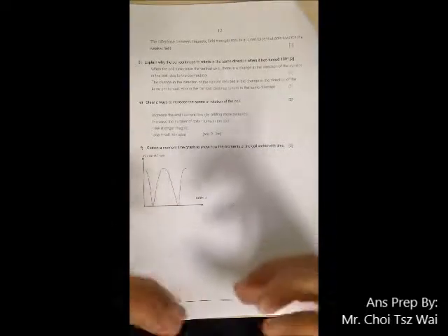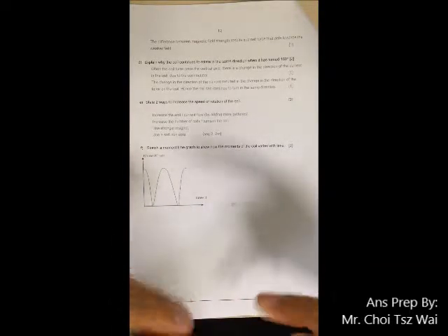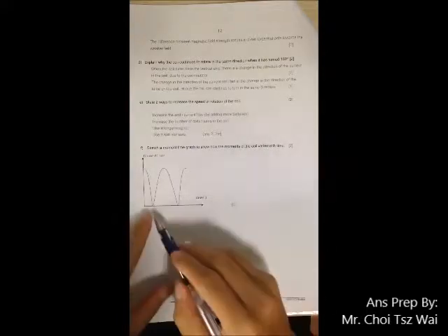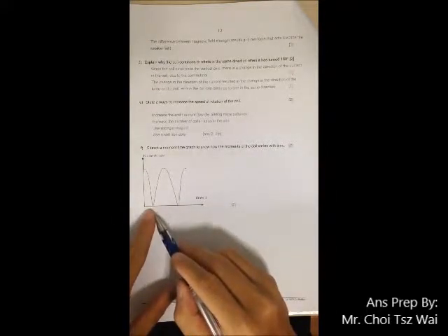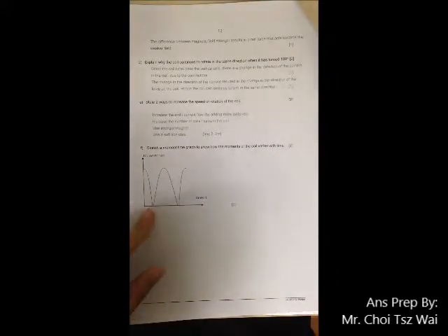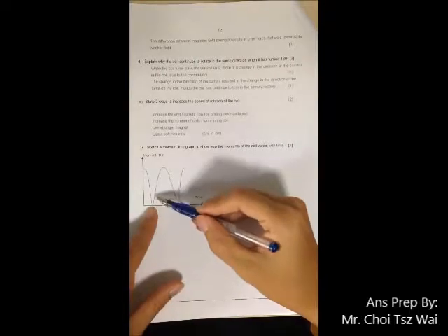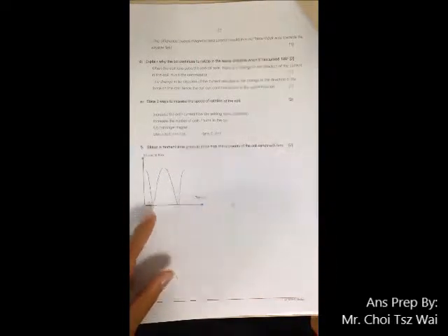Because remember the split ring, there will be a part when the coil has actually no current flowing into it. That's why you suddenly have the zero moment, because when you have no current, there will be no field, and when there's no field, then there will be no interaction of the two fields, and so there will be no force. When you have no force, then no moment. Okay, then after that it will start building up again and become maximum, and then the cycle continues.